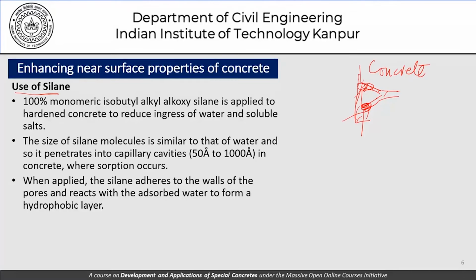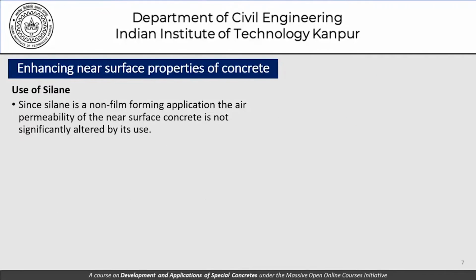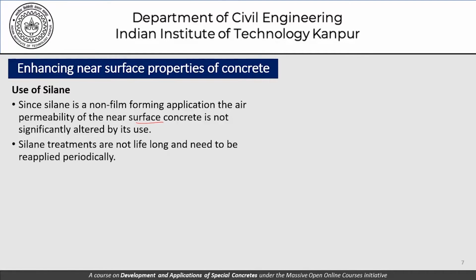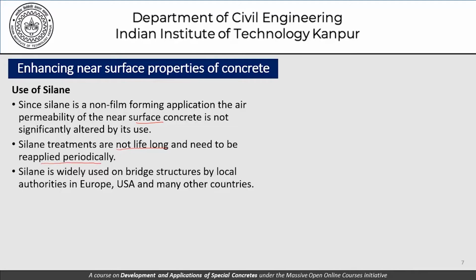When applied, the silane adheres to the walls of the pores and reacts with the adsorbed water to form a hydrophobic layer. Since silane is a non-film forming application, the air permeability of the near surface concrete is not significantly altered by its use. This treatment, therefore, is not lifelong and needs to be reapplied periodically. Silane is widely used in bridge structures by local authorities in Europe, US, and so many other countries, and I would encourage you to look at some literature which describes the use of silane in these structures in these countries.